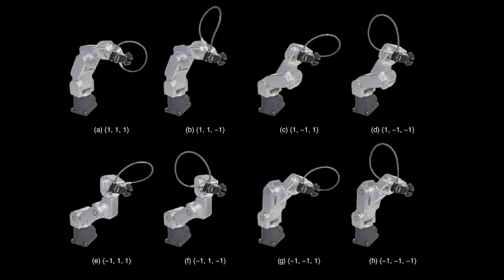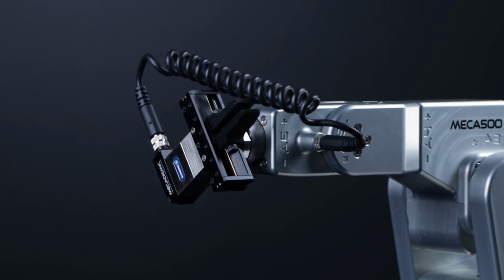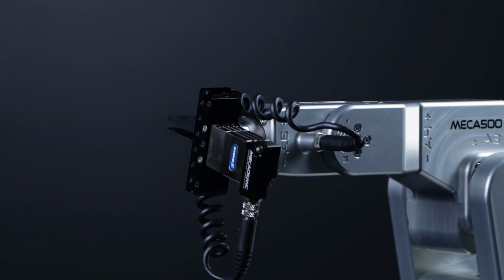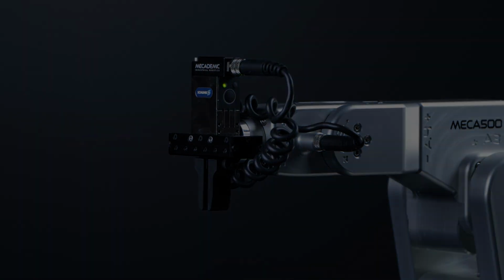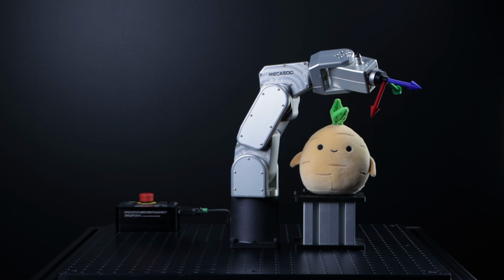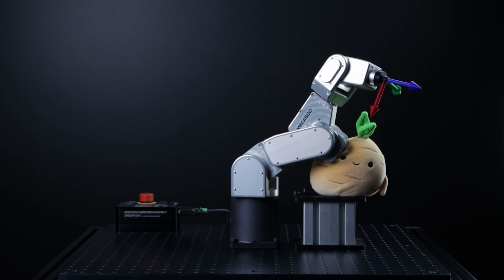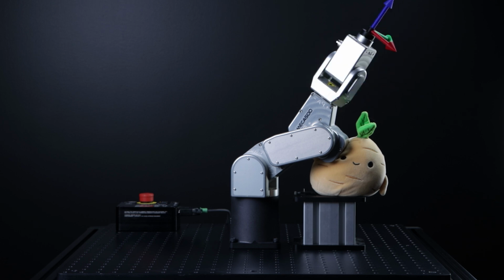The figure below shows the maximum of 8 robot postures for a given end effector pose. However, since joint 6 can rotate multiple revolutions, each posture can have multiple joint values in increments of 360 degrees. While this is not always an issue, it can become problematic in tight spaces where equipment might be next to the robot. So we need a way to tell the robot which solution to use when calculating the inverse kinematics.